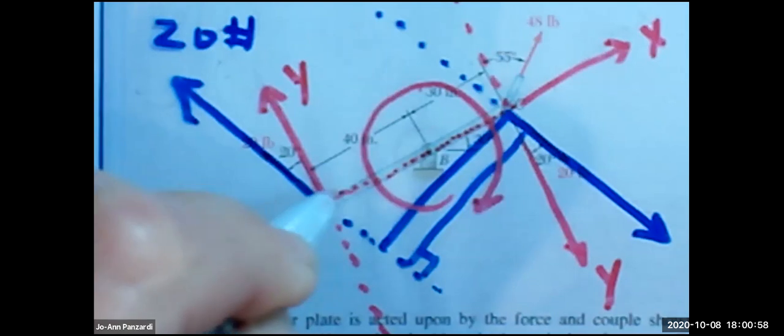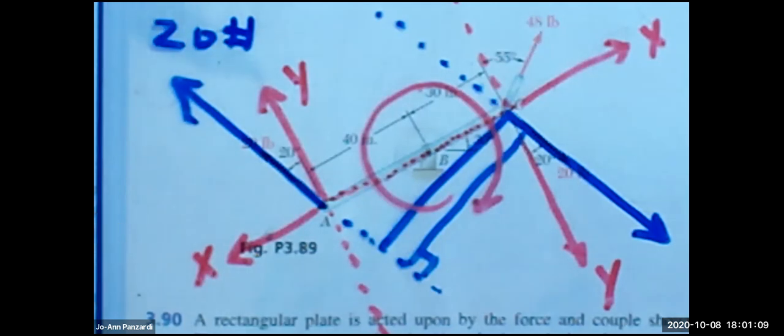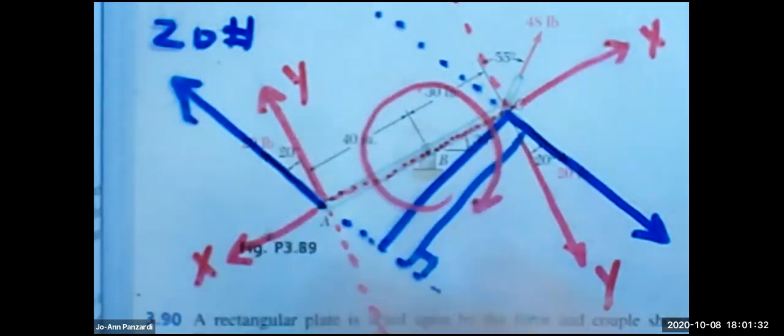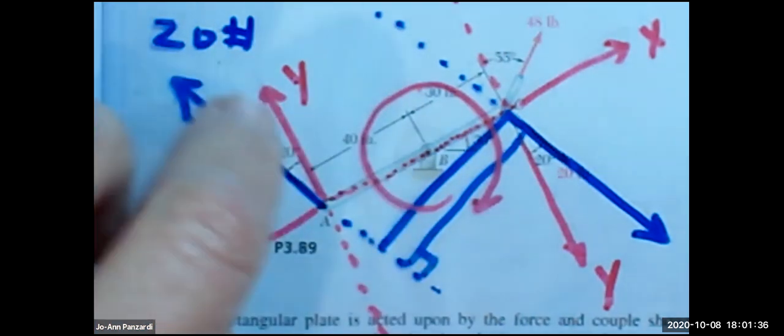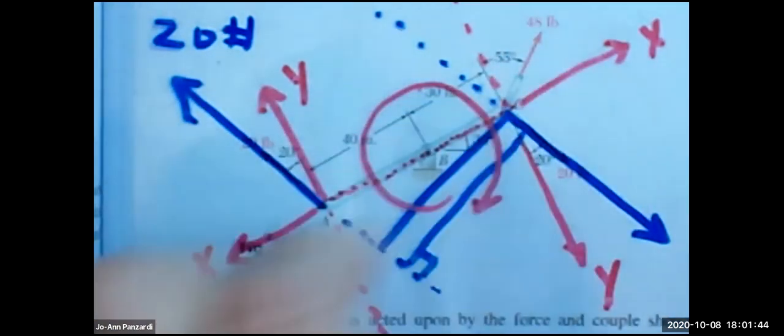Okay. The X couple, the X components of both of them, go through each other. So there's no perpendicular distance. So the X couple creates no moment about the system at all because they cancel each other out. Got it. So you have two options. Either you take the 20 pounds and you find the perpendicular distance to find that it's a negative moment in the system, or if you don't want to do the trig to find the distance, you break the force into X and Y components and then say there are two sets of couples, and it happens that the X couple doesn't create a moment because they cancel each other out.